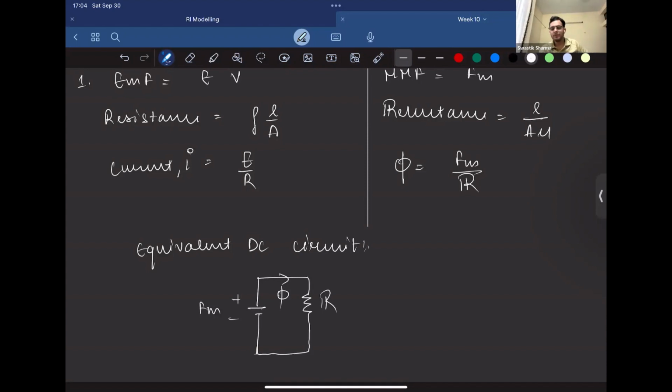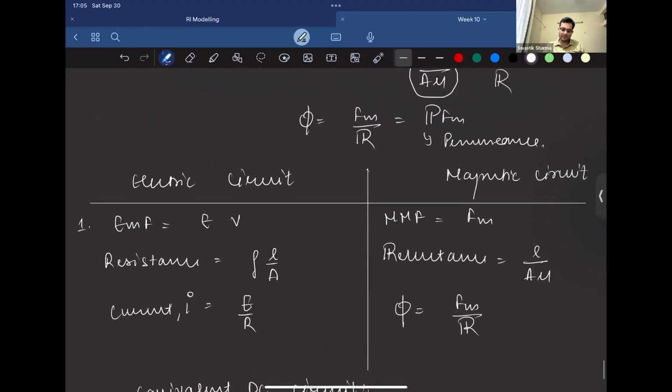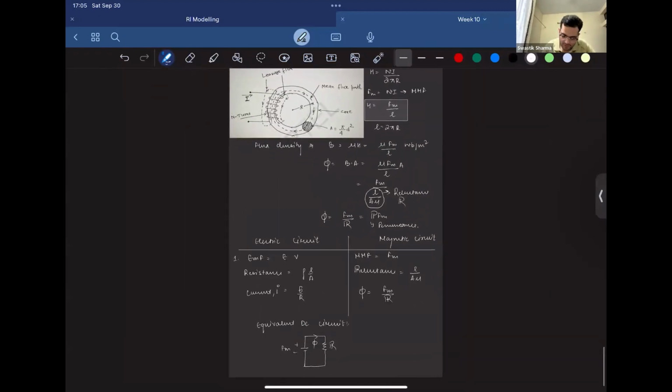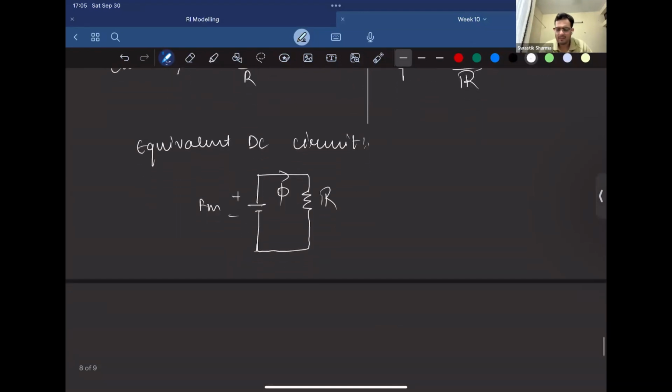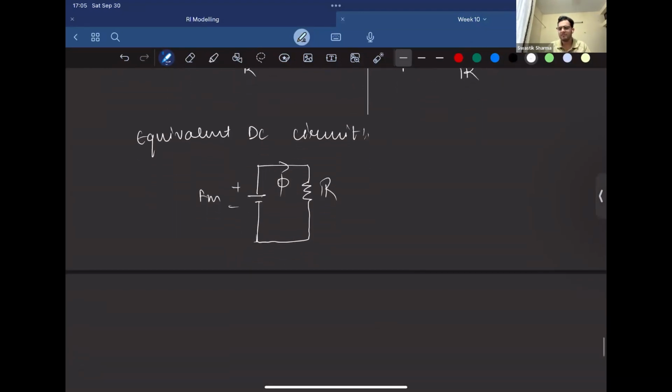That's how we draw parallels between magnetic circuits and electric circuits, and this usually helps in solving questions fairly quickly. You can just calculate reluctance and then the magnetomotive force, and then flux is nothing but Fm upon R. That's why you know how to solve these questions.